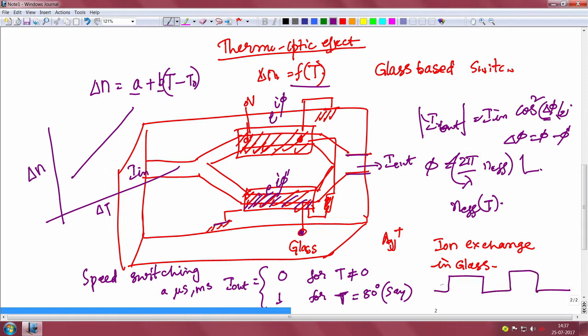This is a switching diagram where you can switch between the 0 level and 1 level. Of course, there will be a small time delay, and switching back also will have a certain time delay, and based on this we can calculate what is the maximum data rate we can go. So, typically it is of the inverse orders. Suppose the switching speed is some Tp, then we can go for switching speeds or frequency of on-off modulation of the orders of 1 by Tp.